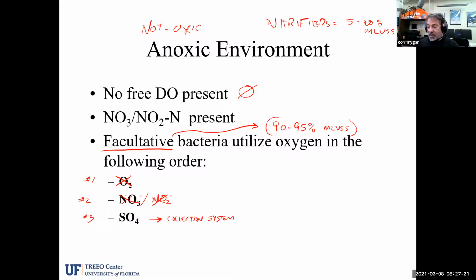And so these bacteria are generally in what's considered a reducive environment, so more capable of reduction than capable of oxidation. So bacteria that are facultative and surviving in a reducive state are able to break apart these compounds into simpler forms. So if there's no nitrate or nitrite present, they can take the sulfate and start stripping away the atoms of oxygen from the sulfate.